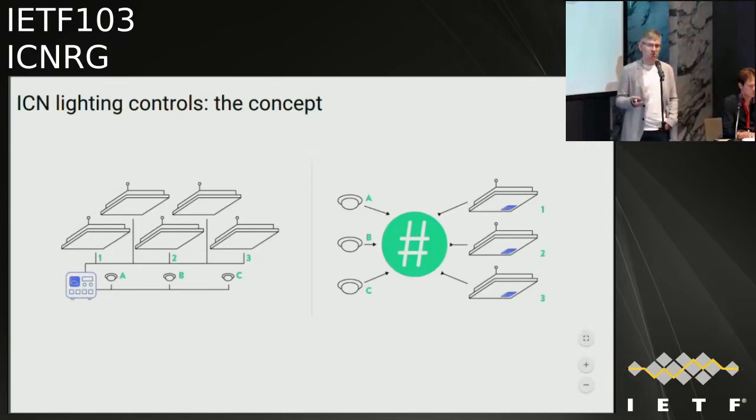And if that information is addressable, then of course, the whole system is naturally easy to configure. And the sensors, they publish. Again, it's really not important how many sensors you have in the room. It's important that they all contribute to the whole block of information referred to as occupancy in the room we are meeting in, right? So meeting room occupancy is our addressable info block, and many sensors in the room contribute to that, publish to that address technically, and the light fixtures subscribe to it.